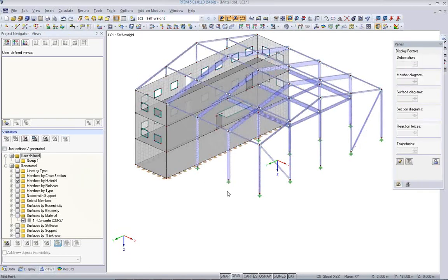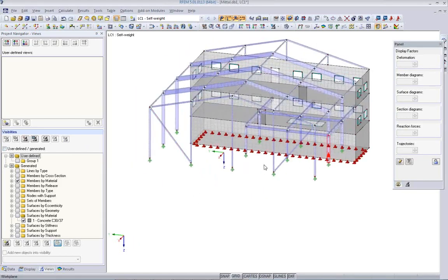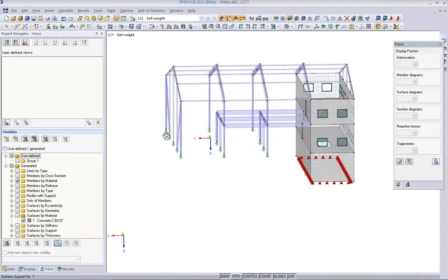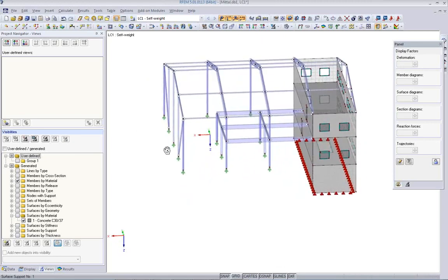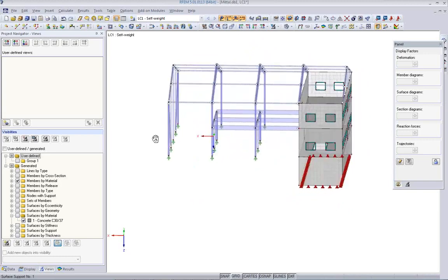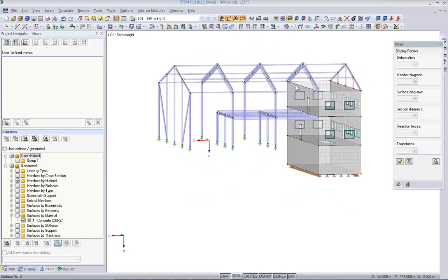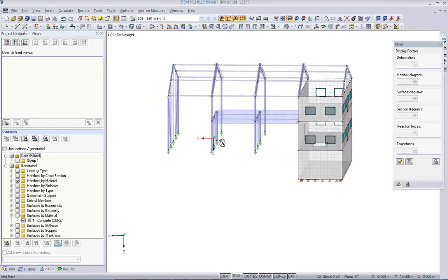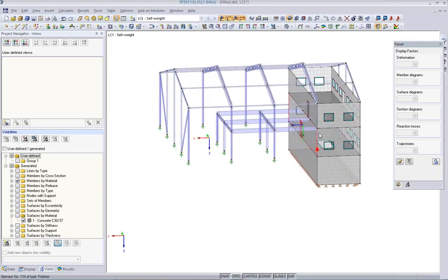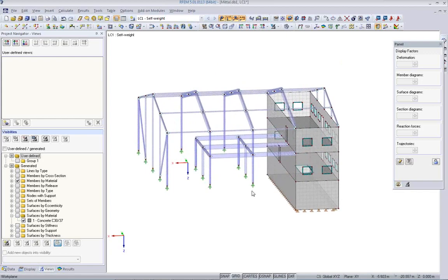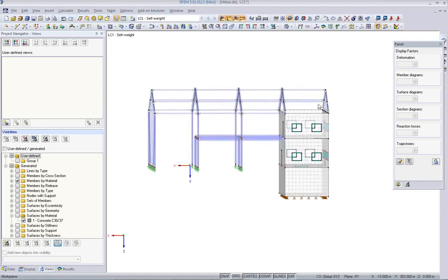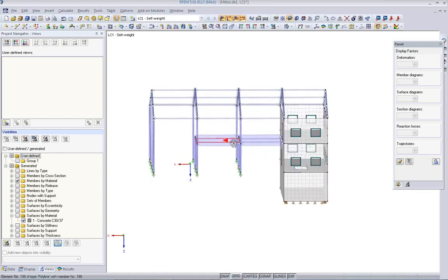First of all, maybe I check another thing from the structural point of view. I need some bracings here in the roof. Typically we have some bracings here. The first level here of the grid is supported horizontally by the concrete part here, but the roof structure maybe is a little bit unstable, and I would like to have a bracing here.